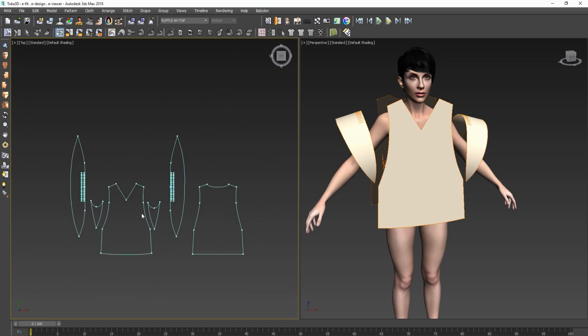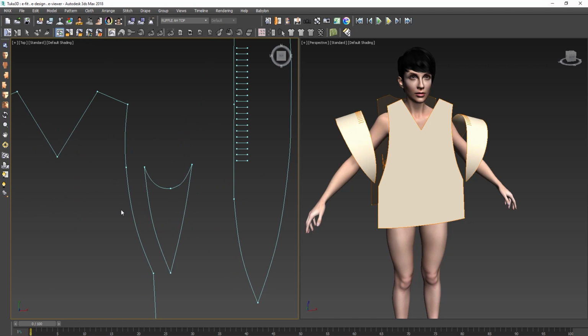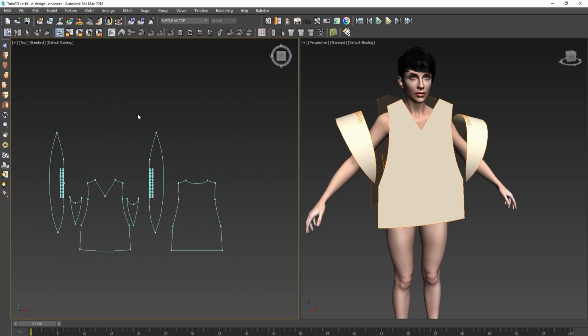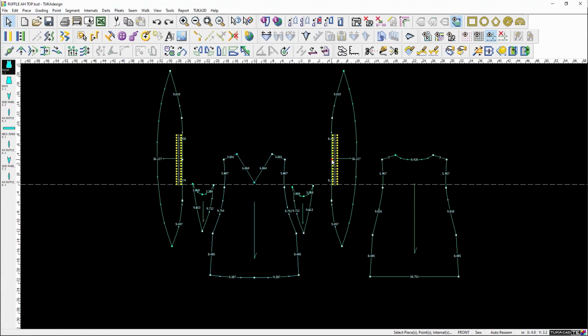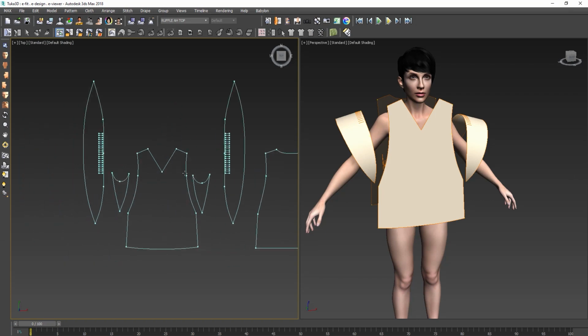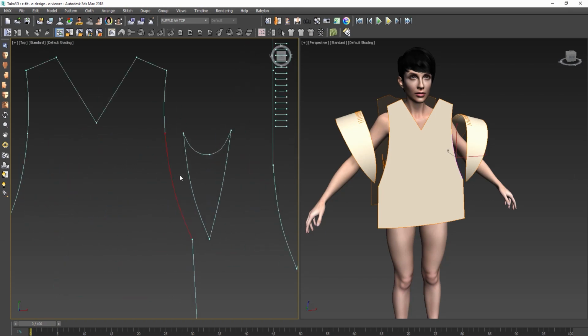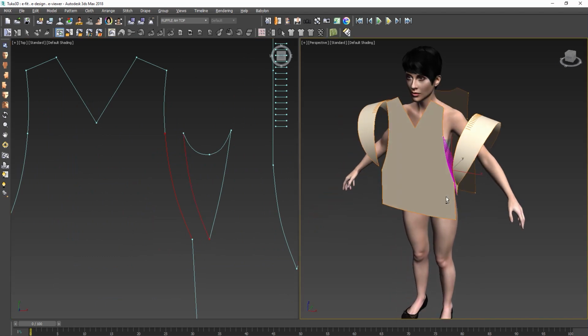Now, like I said, we finished the placement, so we go to the right. Here is the stitch. Once I go to the stitch mode, the left side window becomes the 2D pattern shape window, exactly the same thing. That's why in the beginning I said we rather spend a little bit of time here in 3D. You can click holding Control and click, and then push S, which represents stitch, to stitch.